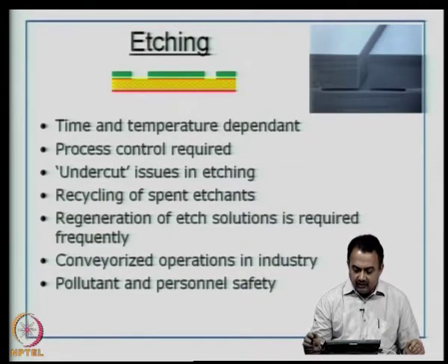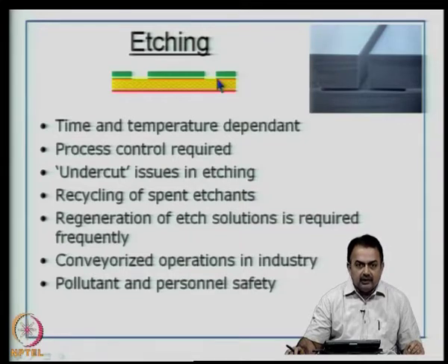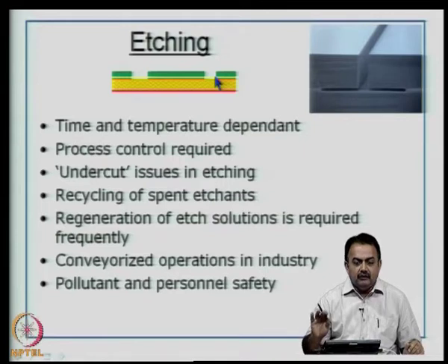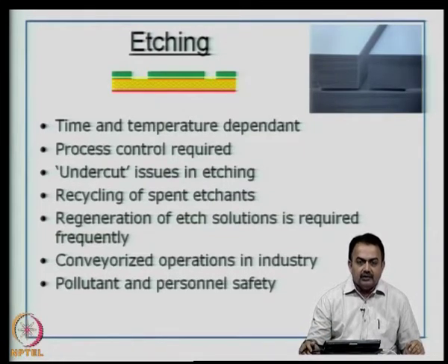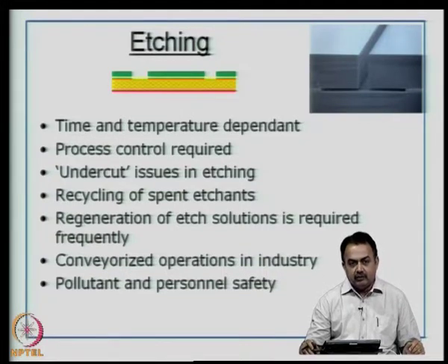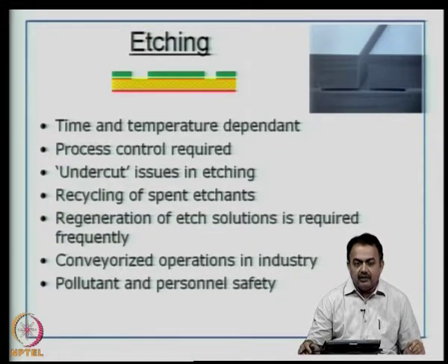Basically, as the name indicates, if the etchant is going to seep under the photoresist material here and remove copper in those areas which are supposed to be protected, then it is known as an undercut. Undercut can be fairly small, or it can be large if your etching controls are not well monitored. So, the idea is you should have minimum undercut on the lines and the pads that you have defined.